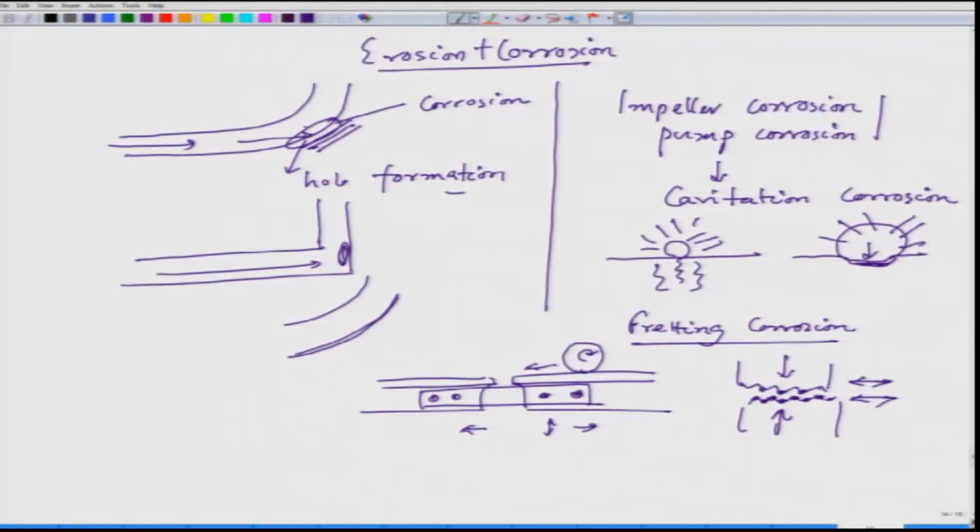And interestingly, you might see that from time to time a railway person comes and tightens these fish plates, because this fish plate loosens, and it loosens because of the fretting action. Okay. And here we also have a fear of crevice corrosion, because these also act as a crevice connection. If water falls, water stays there, it remains stagnant, and corrosion takes place.